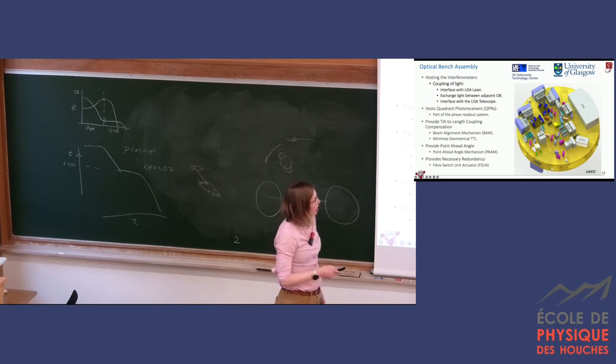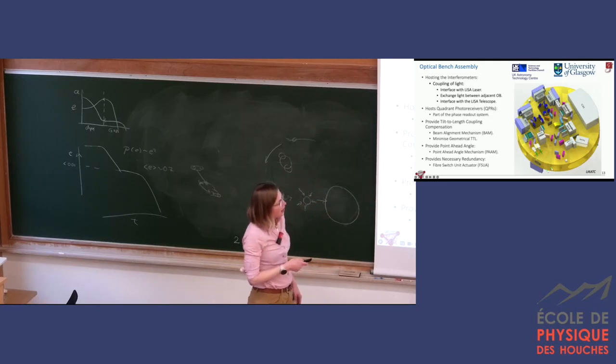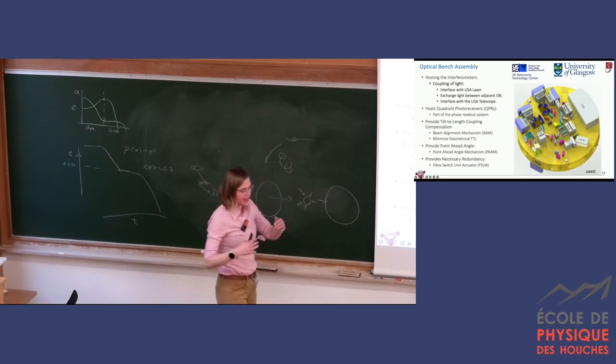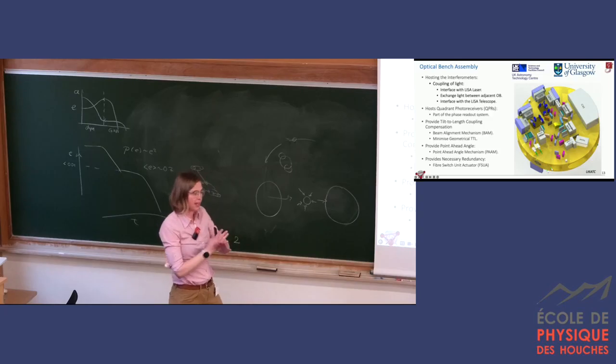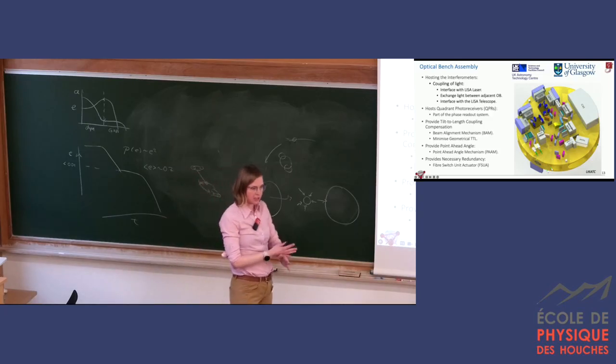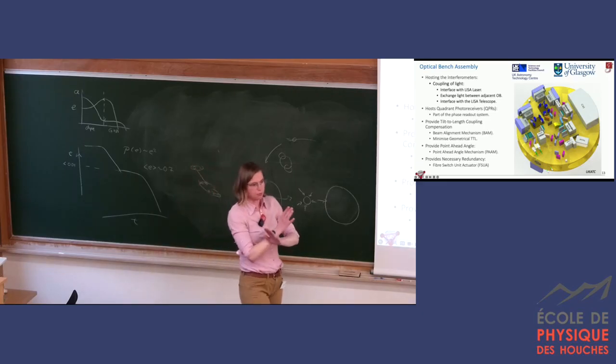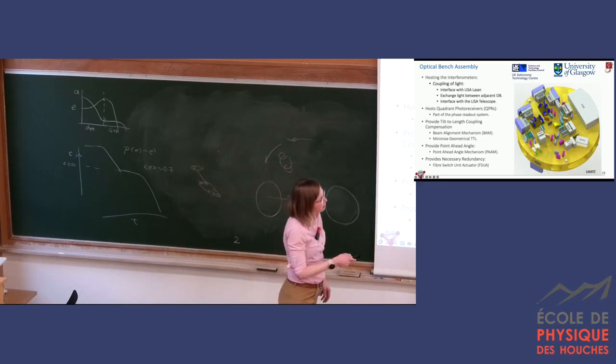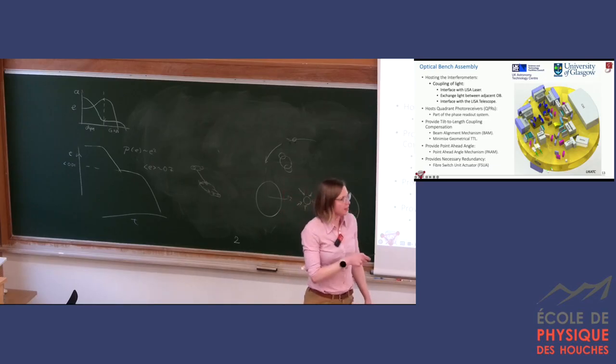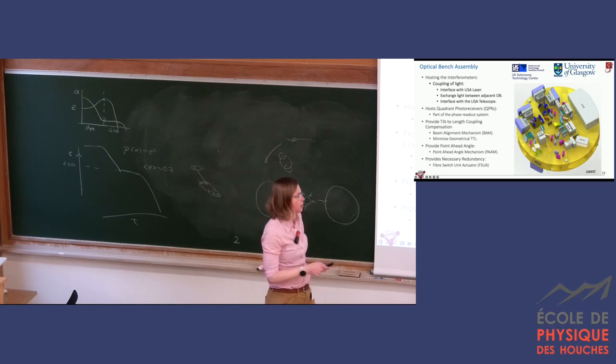Now, the same way we receive the light from the side to this periscope, and the light received and sent is multiplexed via polarization. So there sits the polarizing beam splitter, and there's a half-wave plate that allows us to separate those two beams and sends the received beam here to its beam alignment mechanism, the RX clip, into quadrant photoreceivers, so our eyes that look at the light and measure the beat note.